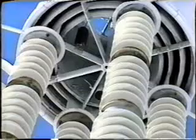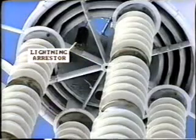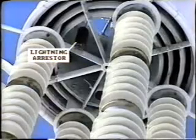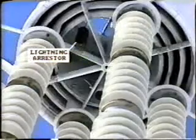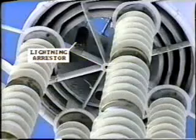Because of the heat in the trap and the operation of the lightning arrestor, the trap can become quite dirty after 1 or 2 years operation. The arrestor can be damaged by doing its job, and this may go unnoticed as it is out of sight. Regular cleaning and inspection is necessary to ensure consistent wave trap performance.